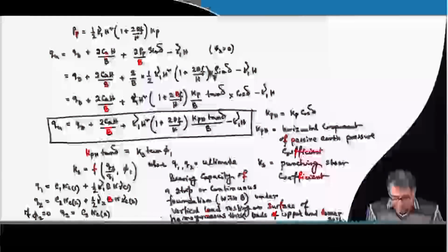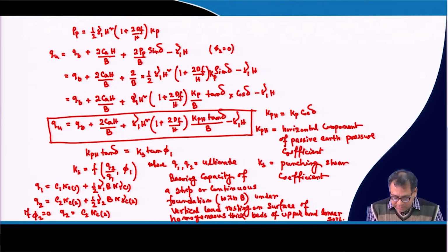Okay. So, now next part, this is the chart where we can determine these values. Now, one thing, how can I get the Nc, N gamma, Nc2, N gamma 2? These values I will get from the chart or the table given by Meyerhof of bearing capacity theories.